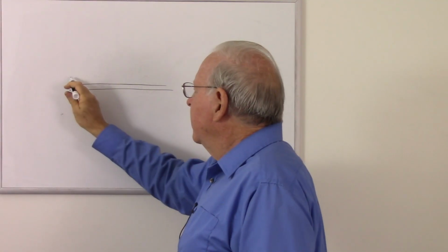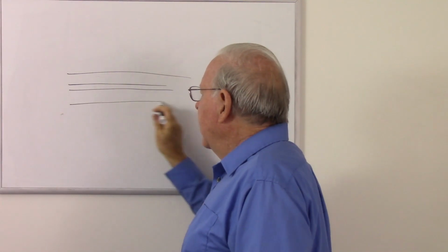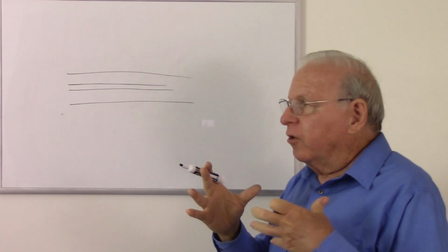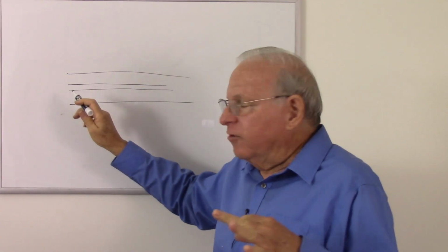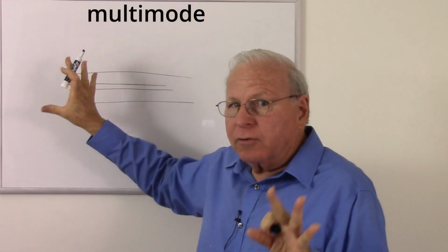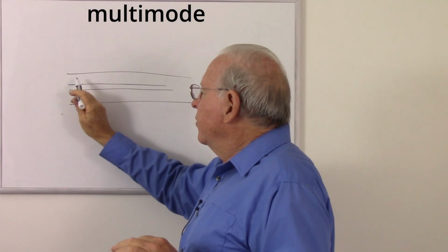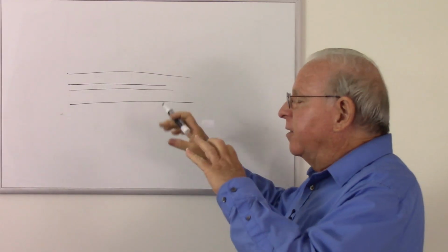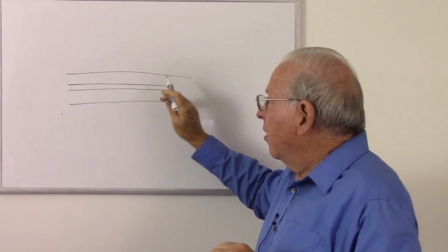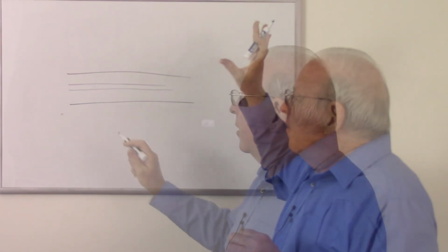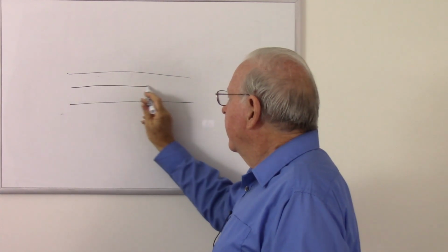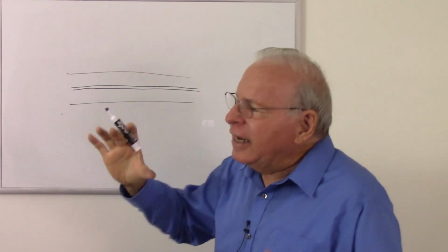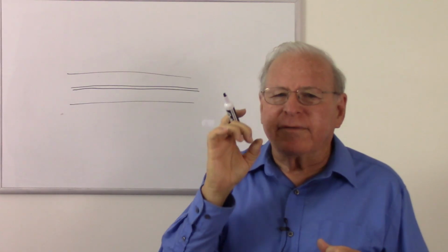Small core, keep our cladding the same size. And so we don't have as many paths. And by the way, those paths are called modes. So we call this fiber, where we can have these multiple paths in there, multi-mode fiber. And so with the smaller core, there's not as much difference in what those modes are, what those paths are, so we mitigate somewhat. So let's make that core diameter something like maybe 8 times the wavelength of the light.